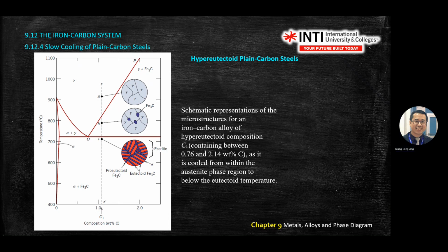Along the boundaries, at this boundary you have gamma plus alpha, and Fe3C at the boundary. Here to here is a bit different from the top and the bottom. The top one you can use a very small dot, but when you reach the eutectoid temperature here, this will become something like pearlite, but a very, very thin purple color along the boundaries. Then when you pass through the eutectoid, you get a pearlite structure.